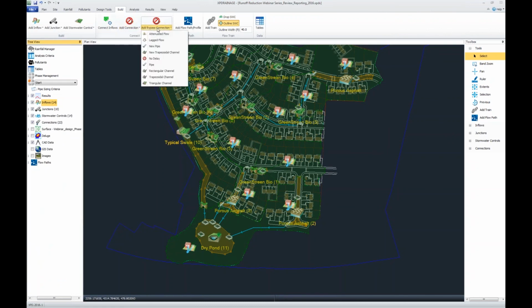There's also bypass systems. It's important to assess what's really going to be in the real world. Almost every case, if you have, say, a bioretention system, it's going to be sized for that water quality event. What happens when it rains, like in Texas, 16 inches in an hour, or in a day?